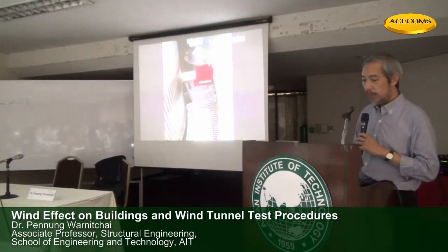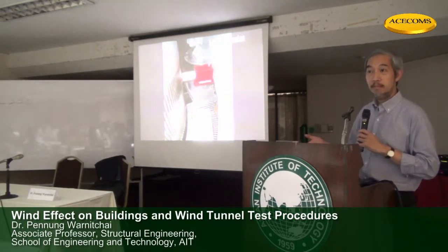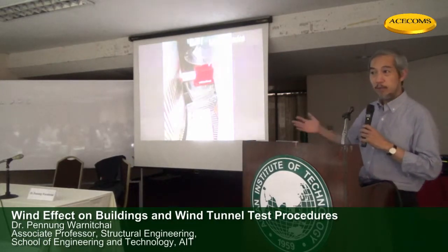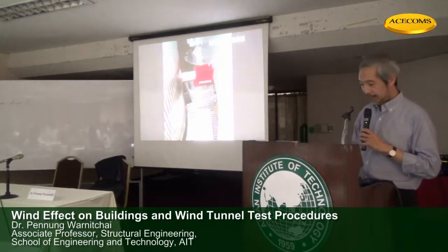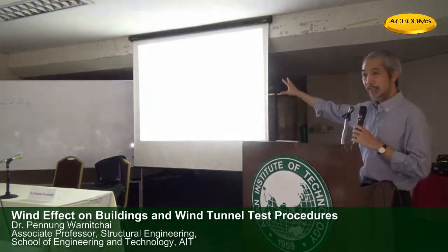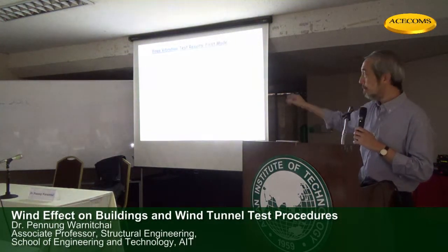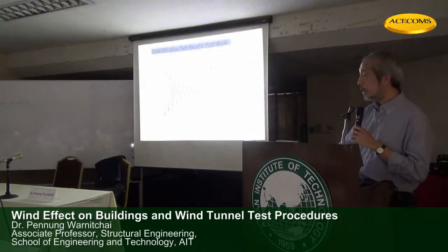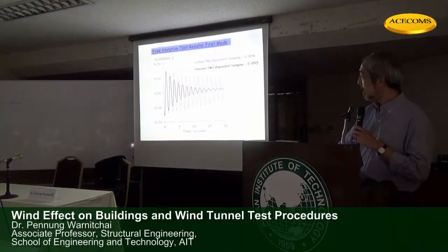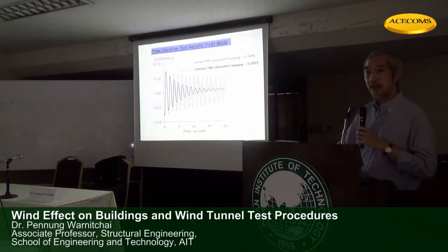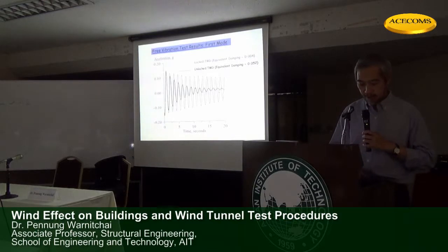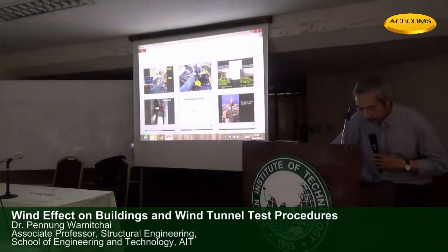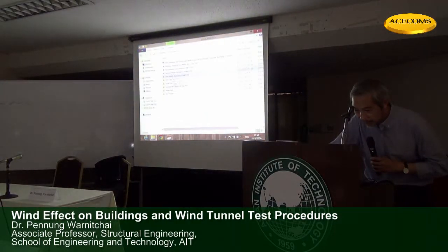When we lock them, we can check the performance of the stack without the damper. And then we remove the lock, allow them to move, and check the performance with the damper. By doing that, we can see how the damping changes. When we lock the damper, it decays very slowly. When we unlock the damper, the structure decays very fast. I mean, it dissipates energy very fast. I'm not sure you can feel this, but I think it's better to see how we work on it.